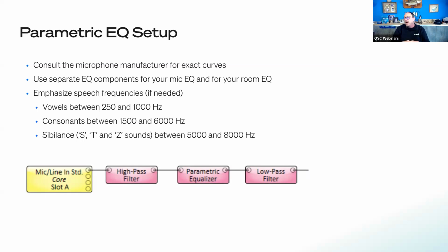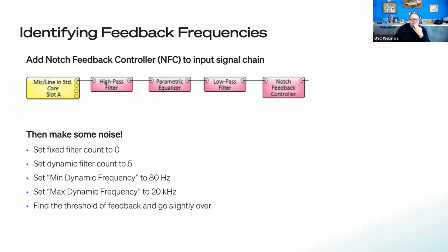That all happens at the higher part of the vocal range, up around 5 to 8K. I actually saw this happen. I was working with a consultant on a project, a really weird conference room, and he said, "Give me a little bump at 7K," and I thought, what? All of a sudden, his vocal intelligibility just popped out. Every room is a little different, but the science behind it stands up.